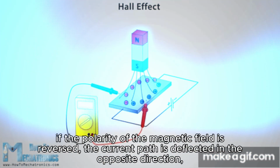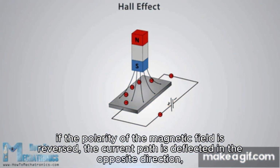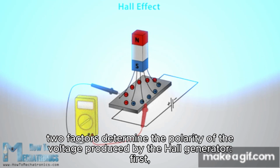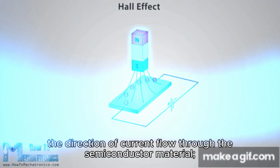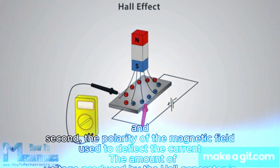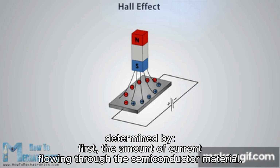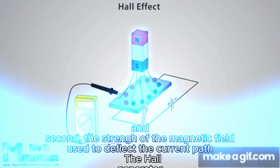If the polarity of the magnetic field is reversed, the current path is deflected in the opposite direction. This causes the polarity of the voltage produced by the Hall generator to change. Two factors determine the polarity of the voltage produced by the Hall generator. First, the direction of current flow through the semiconductor material. And second, the polarity of the magnetic field used to deflect the current. The amount of voltage produced by the Hall generator is determined by, first, the amount of current flowing through the semiconductor material, and second, the strength of the magnetic field used to deflect the current path.